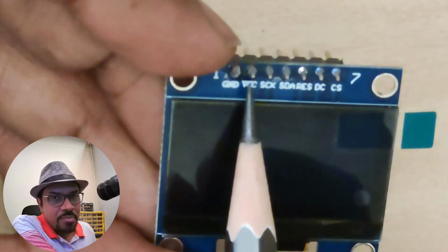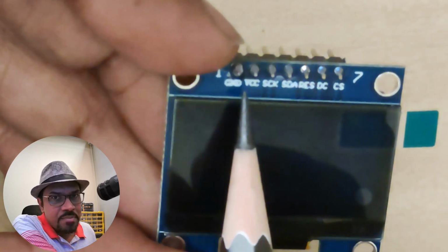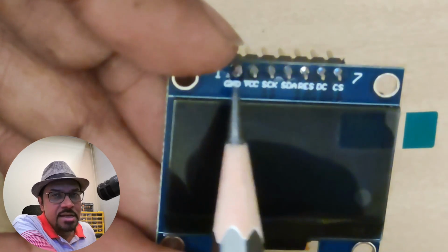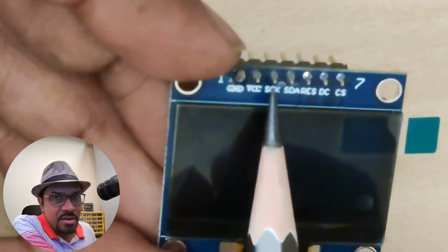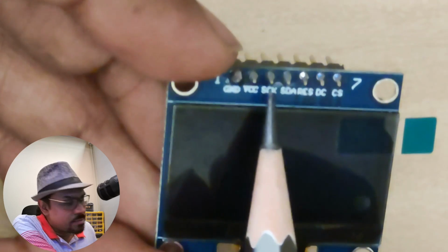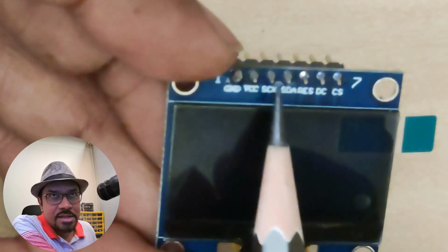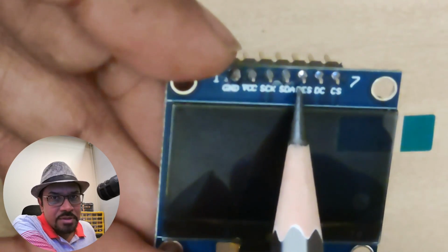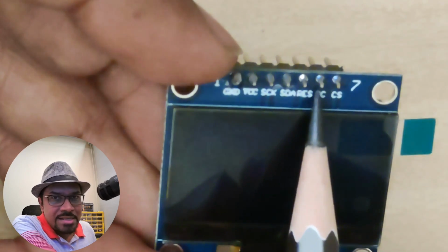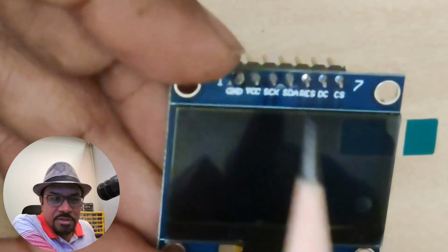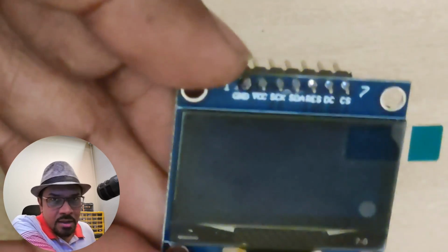You need to connect to the clock pin or SCL pin on your Raspberry Pi Pico if you're going to be using the SPI interface. And you'll also see SDA, which is sometimes labeled as DIN or data in on some of the displays, which is the data pin, right? You also have an RES pin, which stands for reset pin. And there is another pin, which is the DC pin. DC stands for data or command pin, which is meant for sending data or commands.